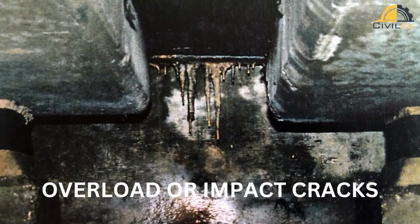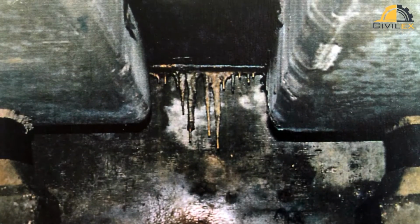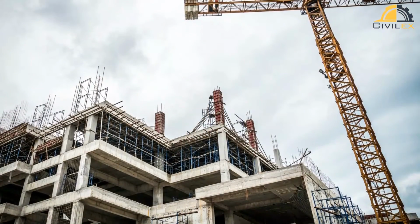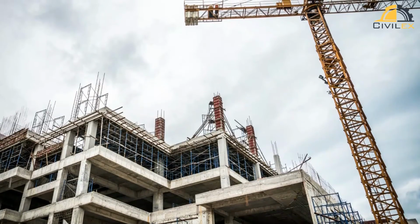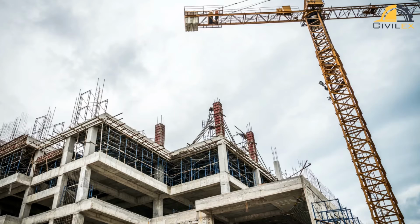Overload or impact cracks. These are cracks that occur due to excessive loads or impacts on the concrete surface. They can be caused by heavy vehicles, equipment, or other objects that exert pressure on the concrete. Overload or impact cracks can be prevented by designing the concrete to accommodate the expected loads or by limiting the weight of vehicles or equipment that will be placed on the surface.